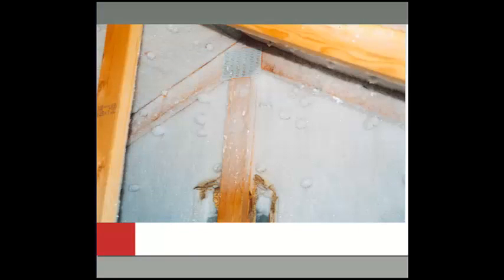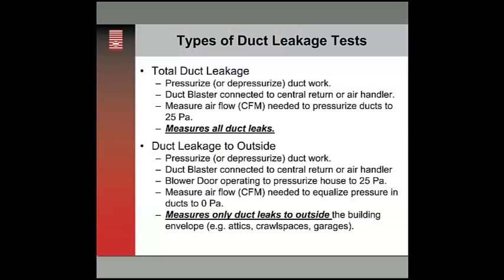And this is a shot a friend from Montana shared of what happens when you have disconnected ductwork up in a bitter cold climate up in the mountains of Montana. You'll have a complete frost zone. You're blowing conditioned air up into bitter cold, and it can be tremendous problems real fast.